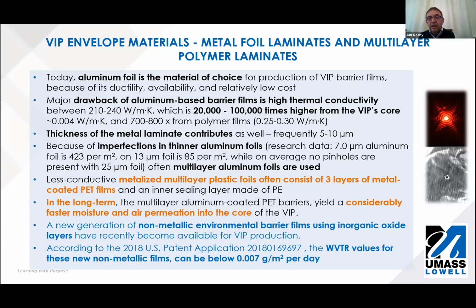So this is a matter of cost and of how much highly conducting metal we are putting on the membrane. To reduce conduction, people designed plastic foil layers which are aluminized. So we deposit very thin layers of aluminum, below 20 microns, and usually people are using 3 layers of aluminized foils to create the membrane. They are worse than really sandwiched thin metal layers, but they are better in terms of thermal conduction and less costly.